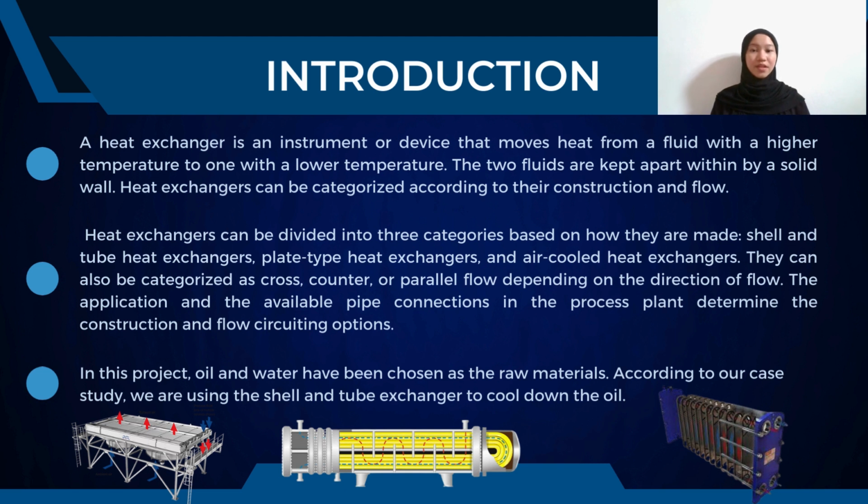For the introduction, a heat exchanger is an instrument or device that moves heat from a fluid with a higher temperature to one with a lower temperature. The two fluids are kept apart by a solid wall. Heat exchangers can be categorized according to their construction and flow. Based on how they are made, they can be divided into three categories: shell and tube heat exchanger, plate type heat exchanger, and air-cooled heat exchanger. They can also be categorized as cross, counter or parallel flow depending on the direction of flow.